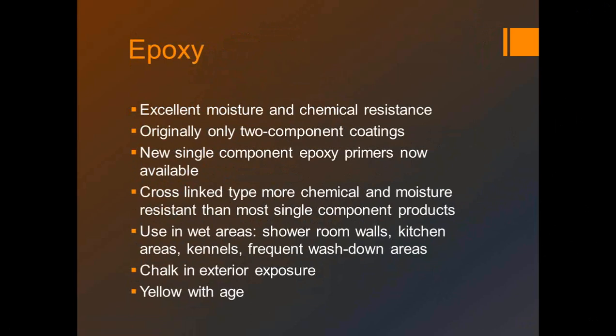We have polyamide epoxies, we have amine epoxies. There's multiple different ones that we use. In commercial construction, and probably places where most of our audience would be writing specifications, polyamide epoxies would be a really good thing, probably one of the better products to use. They're easy to catalyze. They're normally a 1-to-1 or a 4-to-1 ratio to mix together. They do have a pot life, and after so many hours they've lost their pot life and you can't continue to use them. But they do have a good range of color.